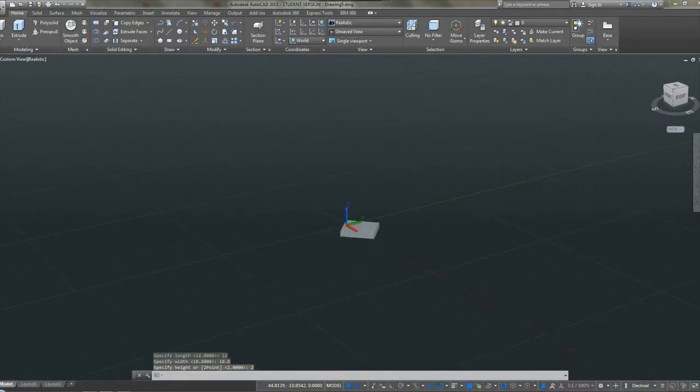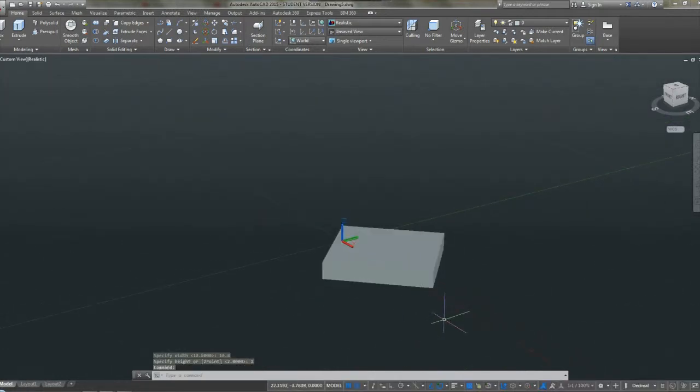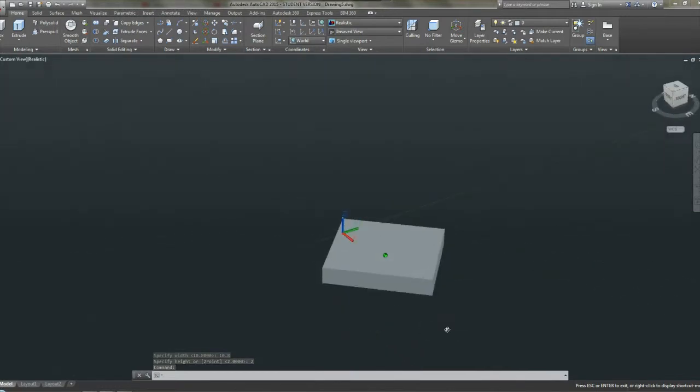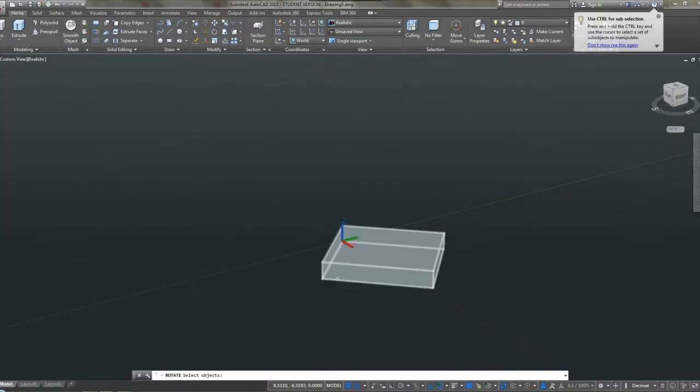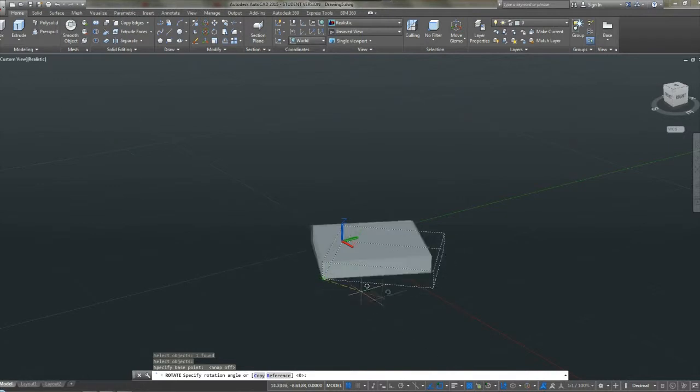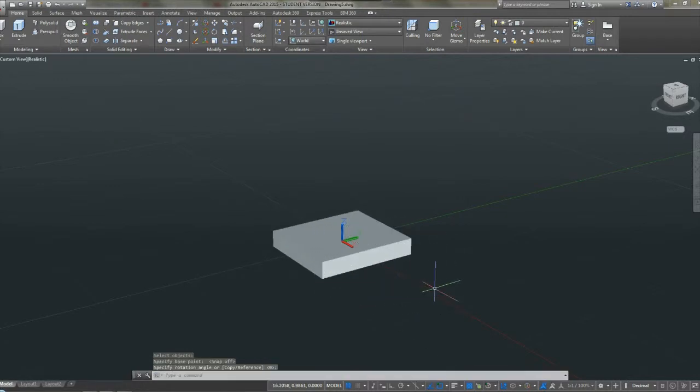You may notice that it comes out not straight, so you're gonna have to rotate it, and to do that you just click rotate, and then click the object, then right click and take off grid snap for this part, because you want to click the corner, and you click this corner and then click the other corner over here, and there you have it.